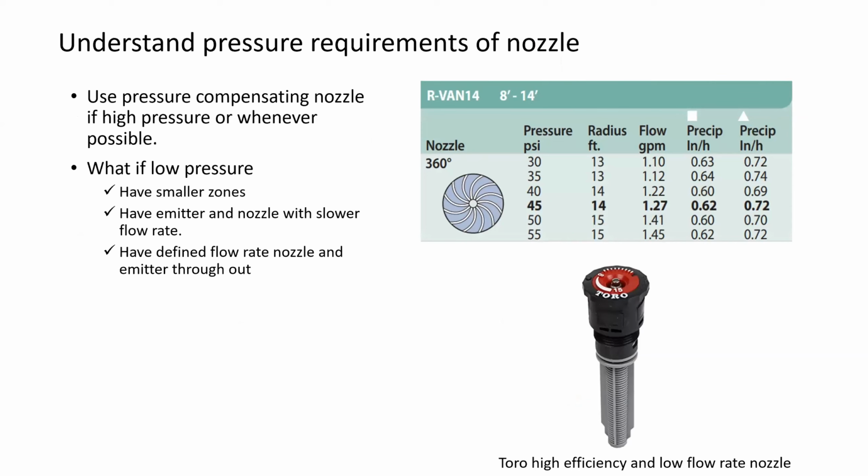Also, you need to understand the pressure requirement for nozzles. And as I already told you, if we have higher or lower pressure than the nozzles have been customized for, then we might not have the desired irrigation efficiency.